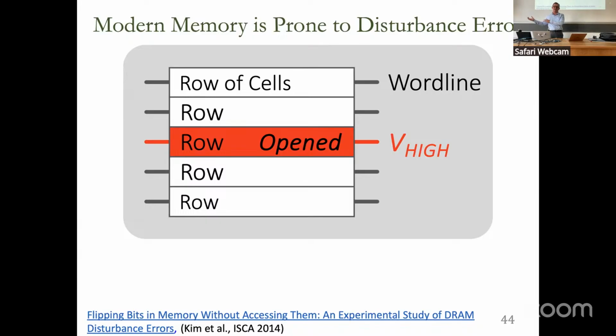And the reason we have the structure is we need to have high density. We don't want to control a single cell when we access something. We want to control many cells so that we can actually amortize the cost of accessing cells, because we want to improve the density. If you are addressing only one cell internally, the peripheral logic to access that cell dominates the cost. If you aggregate such that you can do an access in the two-dimensional array, you can reduce the cost of the peripheral logic, like the row decoder, column decoder, etc.